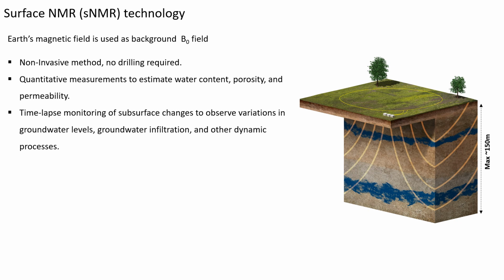So the technology is completely non-invasive. You don't need to drill anything, and you can obtain quantitative measurements to estimate water content, porosity, and permeability of the subsurface. And the technology can also be used to conduct monitoring of subsurface changes and observe variations in groundwater level, groundwater infiltration, and other dynamic processes.